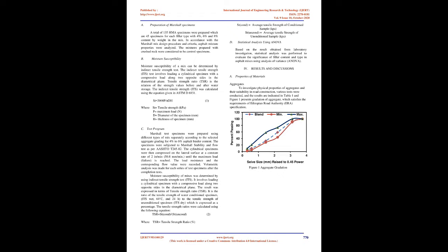18. Adding 6% of glass powder by total weight of aggregates in asphalt mixes led to an increase in the Marshall stability by 15.5% and 9.2% compared with ordinary Portland cement and limestone powder respectively. While the flow decreases by 14.5%, and increased by 4.4% compared with ordinary Portland cement and limestone powder respectively. Use of 8% waste glass powder filler by the weight of total aggregates resulted in asphalt mixes with higher Marshall stability, lower flow, and lower voids in total mix as compared to ordinary Portland cement and limestone powder.